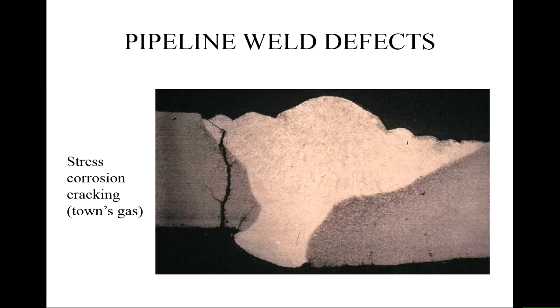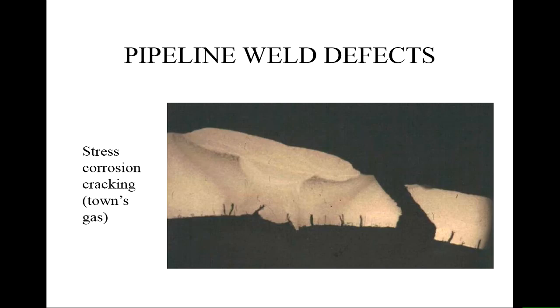So the requirements for stress corrosion are there because we have a corrosive environment. And these micrographs show clearly the inner part of the pipe. What do you notice? A lot of corrosion cracks at all places, and obviously one of them eventually propagated all the way through the pipe wall.